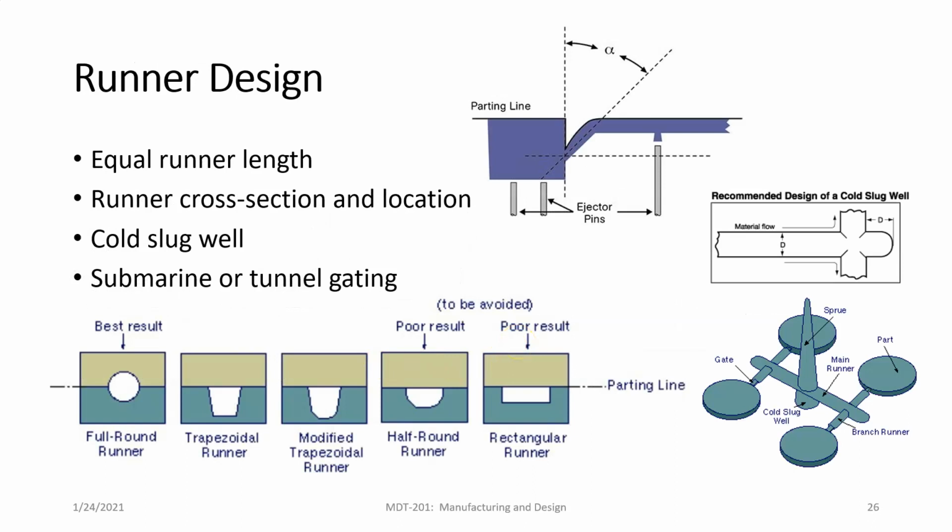So looking more closely in at the runner design, we have different shapes for how the ejector pins are going to push the part out, different angles that we have to consider for the part, different geometry for the gates and runners, whether the runner or gate, I should say, is below or split 50-50, what the shape of the gate is, right?